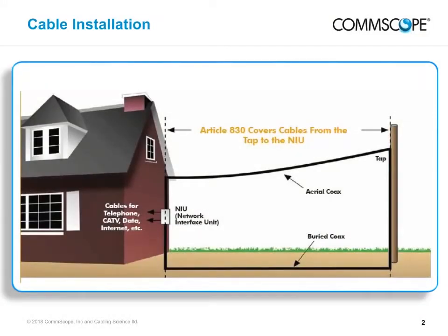Cables used are placed underground in new or existing tunnels, conduits, or ductwork, or they are directly buried. Alternatively, they can be installed aerially between buildings. The environment they will be exposed to is the key factor in selecting outdoor cables and deciding how they should be installed. Weather, in particular likely storm loading, is the key environmental factor for aerial cabling. All factors being equal, underground installations using ductwork are the most popular method, although any of the other methods can be used if they are more cost-effective or appropriate to the location.